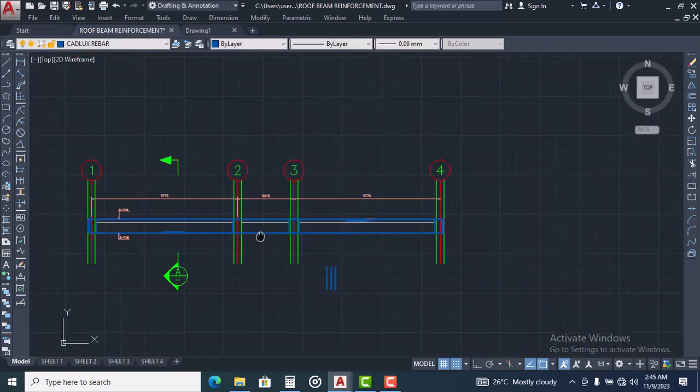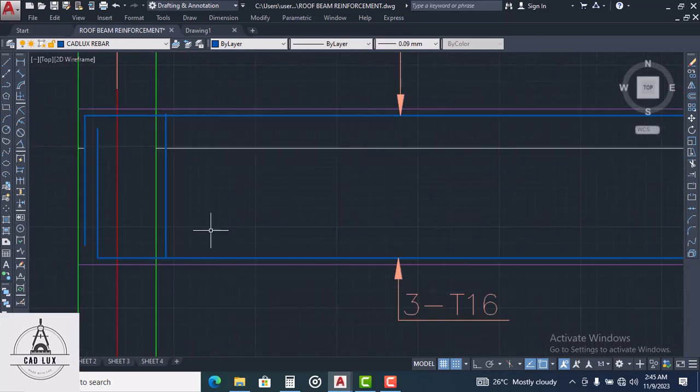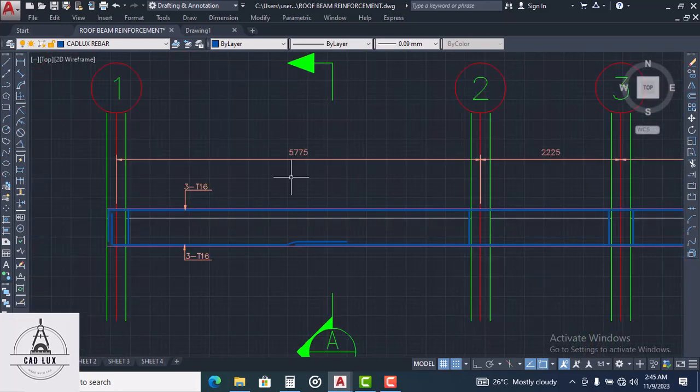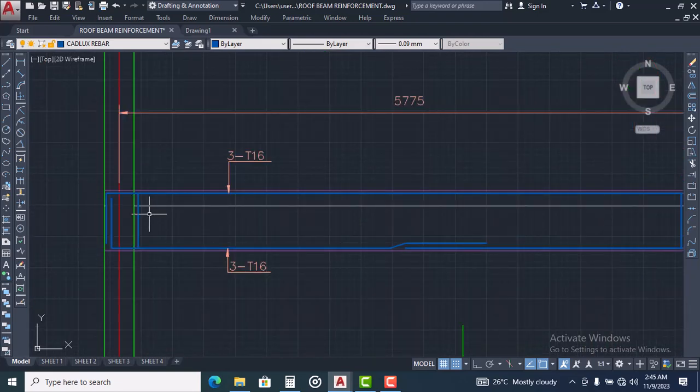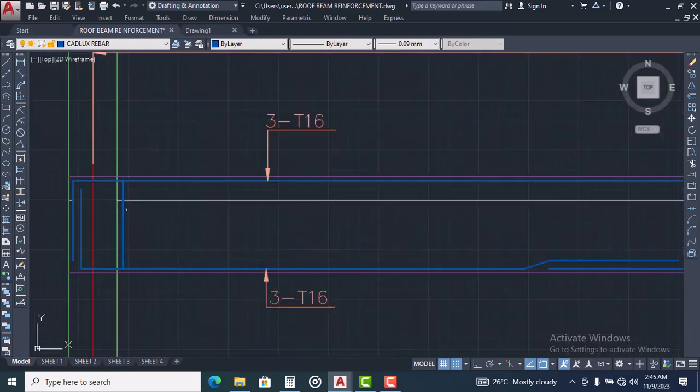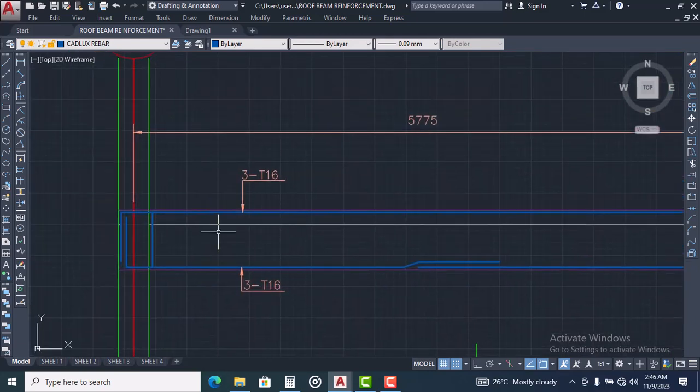So for the stirrups, one thing about links, one thing about stirrups, is that between the stirrups there's something called the spacing. The spacing is the distance between the stirrups, aligning between each of themselves. That's the spacing of the stirrup. This is mainly gotten from the structural design. You understand? Some use 150, 175, 200 spacing.